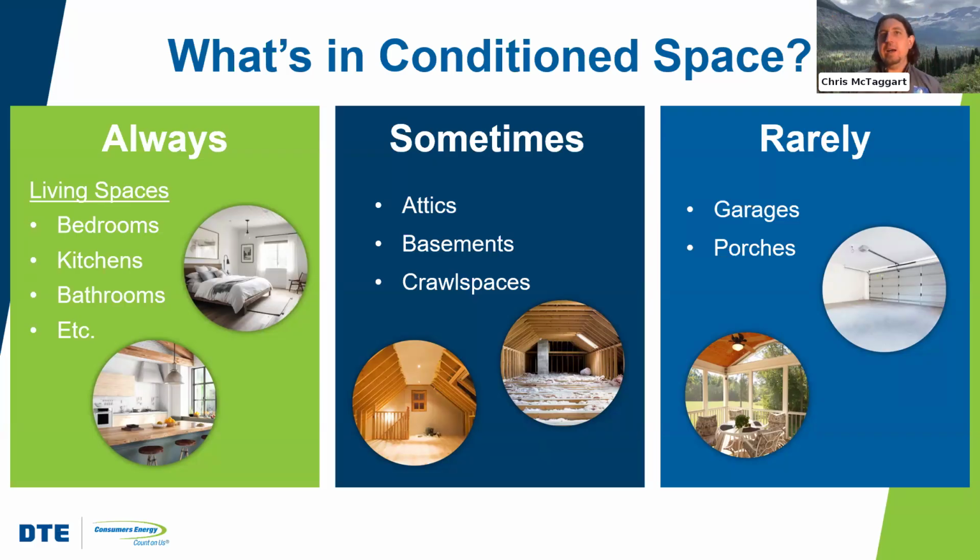Basements, same deal. And that happens a lot in Michigan. Oftentimes we have unfinished basements that are semi-conditioned. Ideally, you'd throw a register or two down there to directly condition it, just to keep it at a similar temperature as the rest of the house. But regardless, especially here in Michigan, we've got basements that are, generally speaking, within conditioned space.